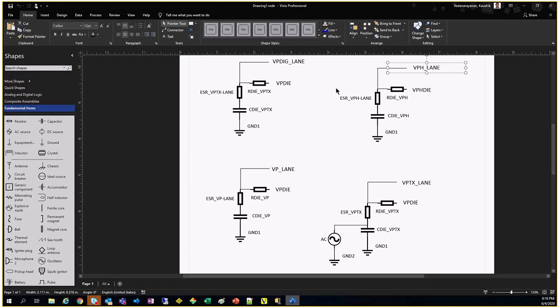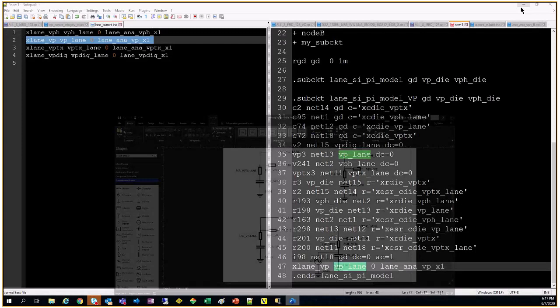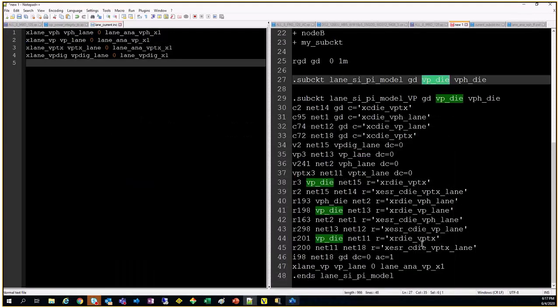So that one sub-circuit has all these 4 RC combinations, no? I'm going to only hook up current over here at the VP name in this sub-circuit, because then only this will get excited. Others will not get excited; they remain dummy. And in my main deck I will connect to the VP underscore deck.